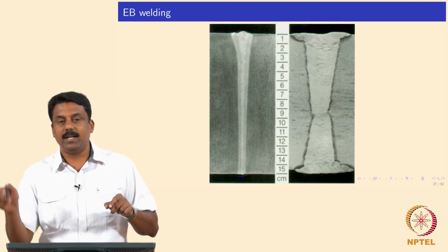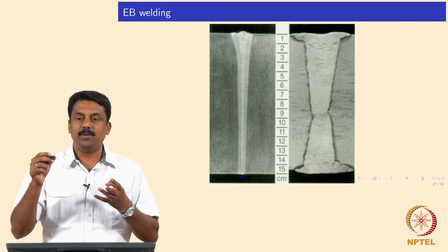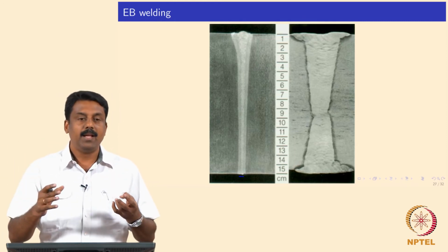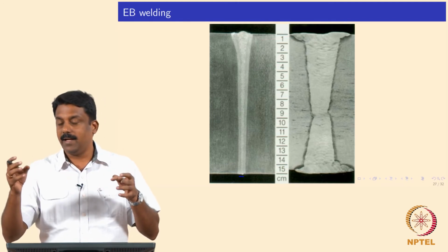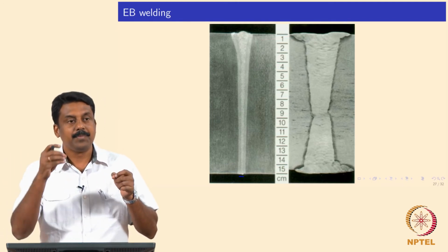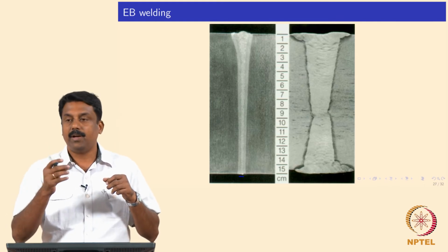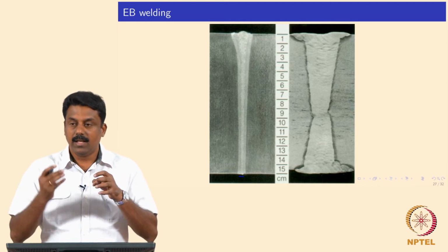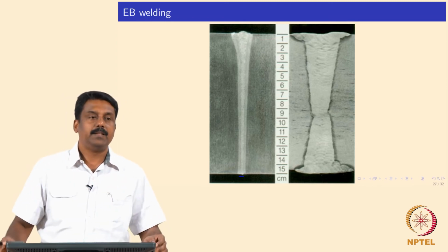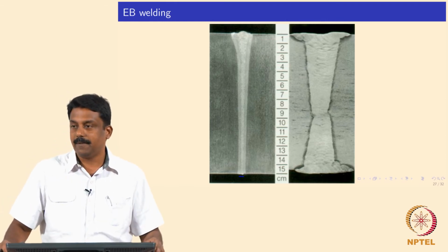If you are doing it in pipelines, you need to defocus the beam or maintain a low power in such a way that the molten metal is heated and you are not forming any keyhole. You are working in conduction mode, and then the liquid can fill the hole. Otherwise, you will see a pinhole at the end of the weld.